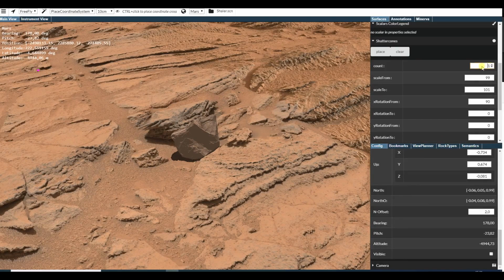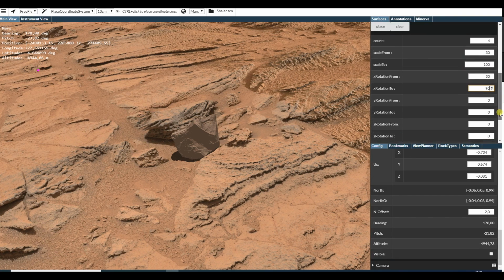In the next step, we set how many objects should be placed automatically. We adjust geometric parameters such as the size range in percent and rotation intervals in degrees to constrain random variations. The maximum distance from the viewpoint can also be defined, as well as the intrusion depth.